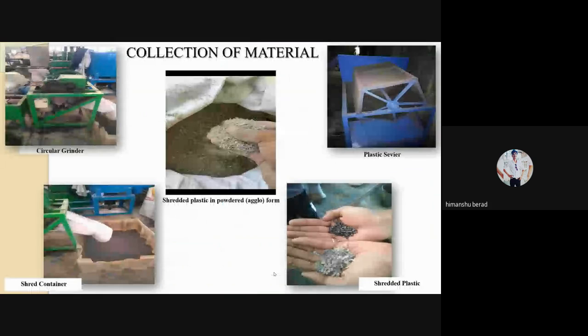So going with our PPT, you can see, firstly, for every project we have to collect the material. We have cement, fly ash, and fine aggregate with us, but we have to find what plastic we are using in our brick to vary the properties from our side. So firstly, for knowing more about this plastic and its proportion, we visited the Kalamna plastic industry situated at Nagpur. They gave us a brief about how plastic is shredded and how it is mixed, and how we can use it in our mixed design, since there is no proper mixed design of such cement, plastic, and aggregate containing bricks. So we took a brick from that, and we use shredded plastic in our design.